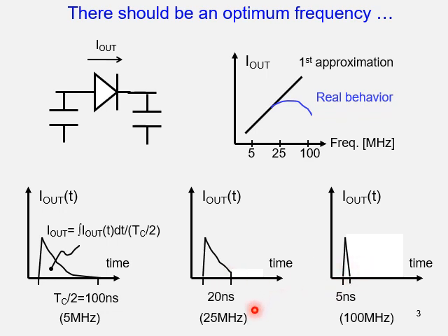And furthermore, if you extend the clock frequency, then probably the output current is limited by the clock half cycle. So at this point, the amount of charge couldn't be sufficient to get the sufficient output current. So you would expect that the behavior is like this.